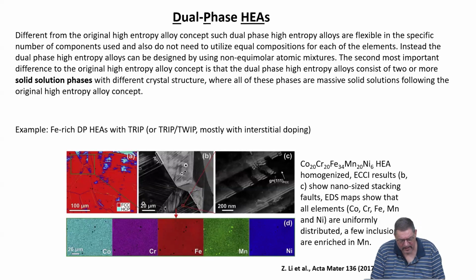And one aspect here which people emphasize is that in these 2-phase, dual-phase high entropy systems, they can also get transformation-induced plasticity TRIP or twinning-induced plasticity TWIP effects. And this is what you can find in these high specialty steels, which are very expensive. So there you pay by kg and not by ton.